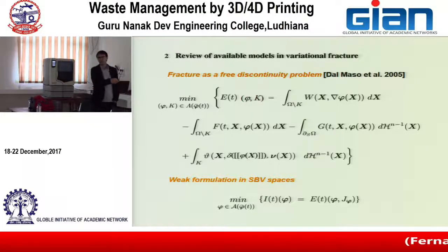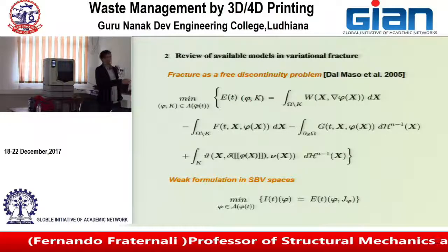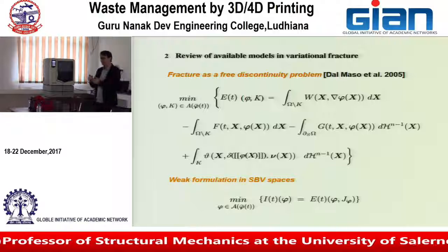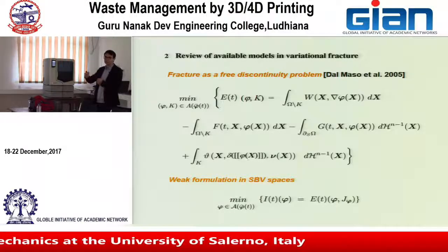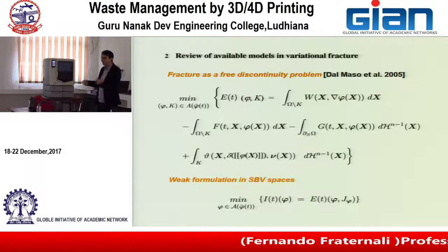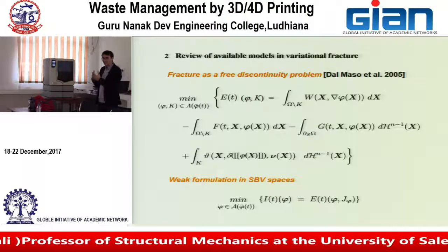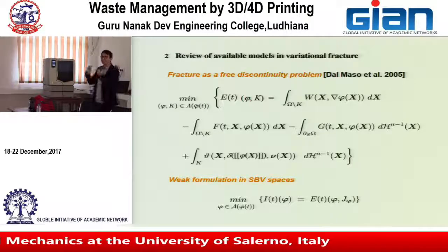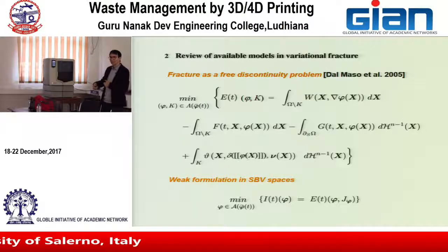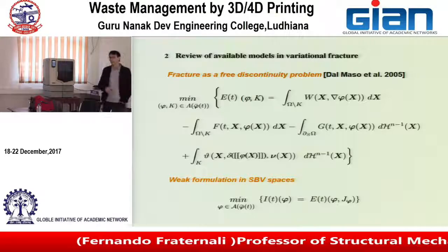Let's forget about those two parts. You can basically neglect those two terms if you are applying a displacement loading, assuming that you grip your specimen in a testing machine and you apply a displacement loading. You won't have body forces and you won't have surface tractions because you are applying displacement and not forces. So assuming displacement controlled loading, those two terms are missing, and only the first and the last term survive.